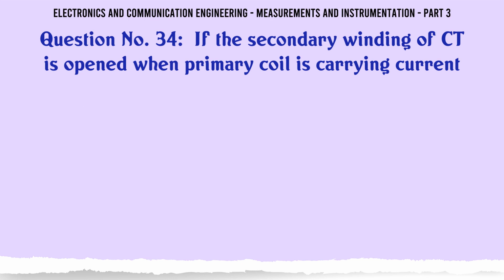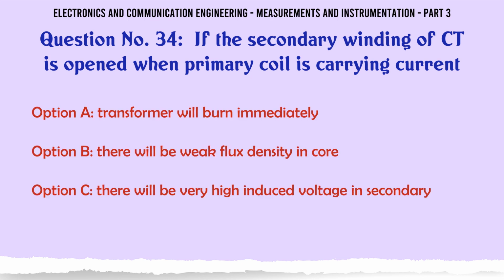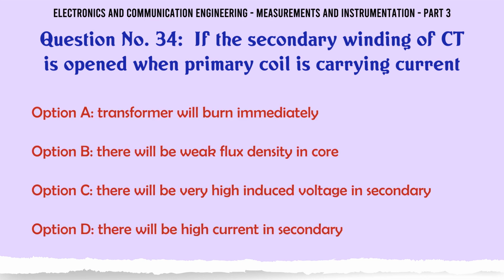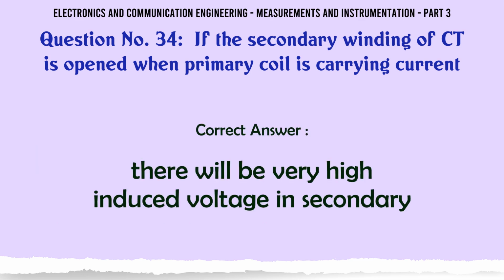If the secondary winding of CT is opened when primary coil is carrying current: A. Transformer will burn immediately. B. There will be weak flux density in core. C. There will be very high induced voltage in secondary. D. There will be high current in secondary. The correct answer is there will be very high induced voltage in secondary.